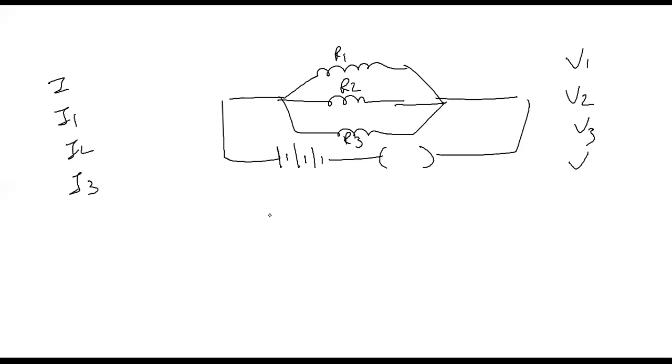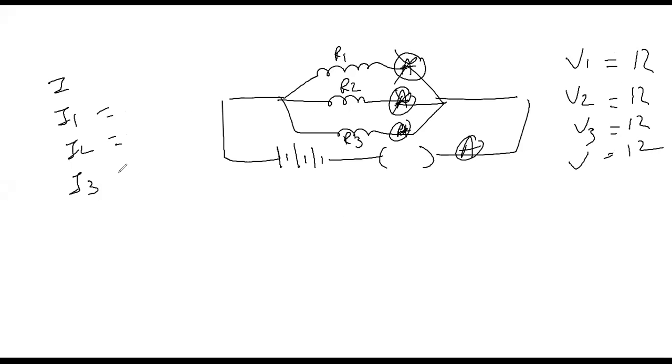Similarly, once I will connect the ammeter over here, it will show me only current through R1. Remove from here, connect here, it shows only current through R2. Remove from here, and finally show here. This time, my voltage every time was the same. Say 12, 12, 12 and 12. But current changed. One, then sometimes it was 2.2. Here it was 3.8. But total current was 7.